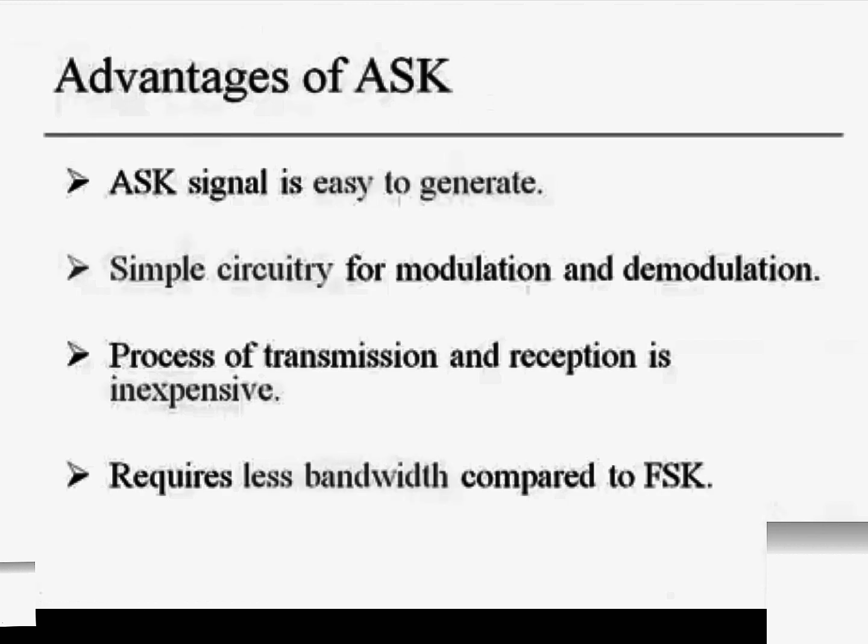Let us see now the advantages of the ASK signal. The major advantage of ASK is that this signal is easy to generate, and because of this, the circuits for modulation and demodulation of the ASK signal are very simple and less complex, and thus we can say it is inexpensive. The bandwidth requirement is also less compared to the FSK signal.